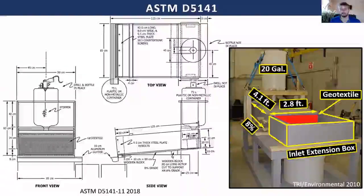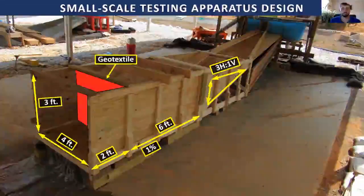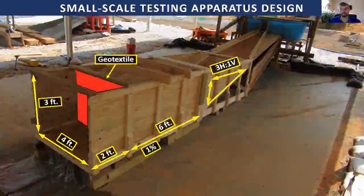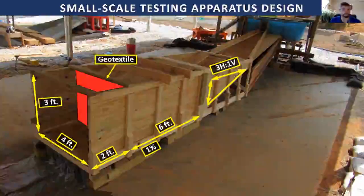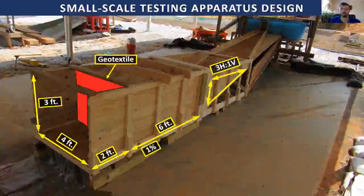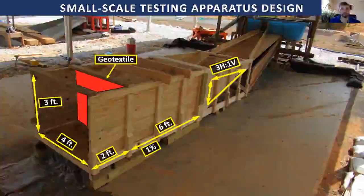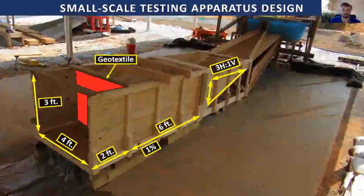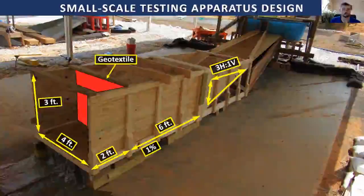What we set out to do is to develop a more in-depth testing process where we can actually have full-scale geotextile installations, but do it on a small width component, essentially. So what we developed was this testing box, where I introduce water and sediment. It comes down a 3-to-1 horizontal slope, which we designed based off cut and fill operations, typically on roadside construction projects. Then it enters the bottom portion of the box, which is on a 1% slope, and we install a geotextile that is actually 3 feet in height.